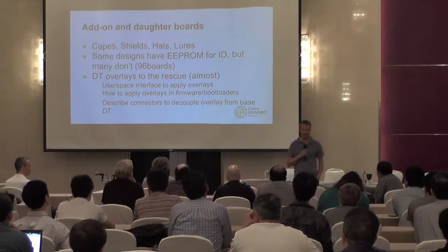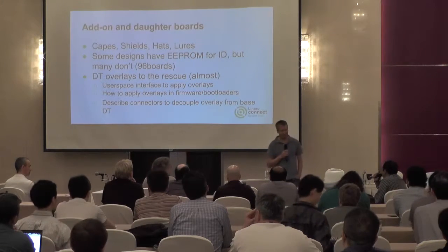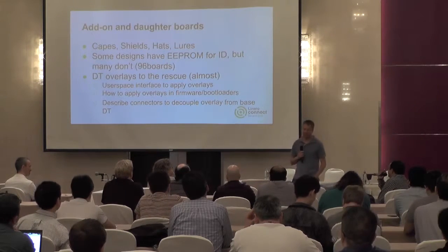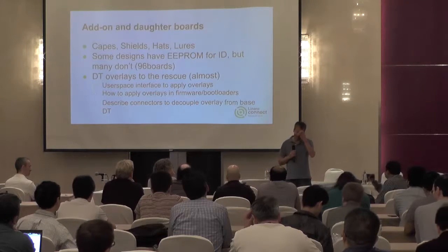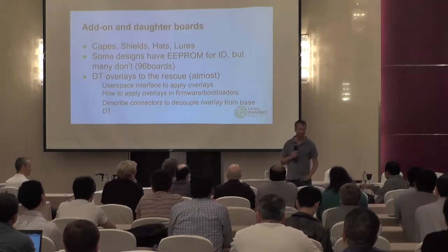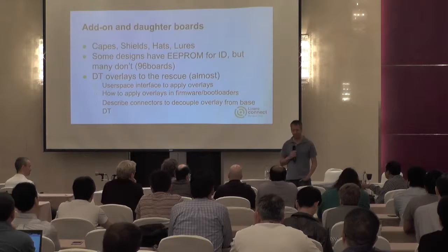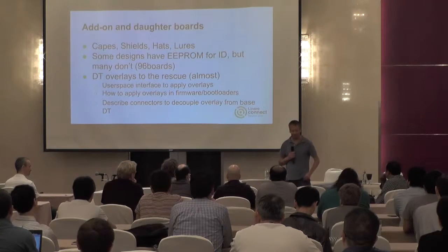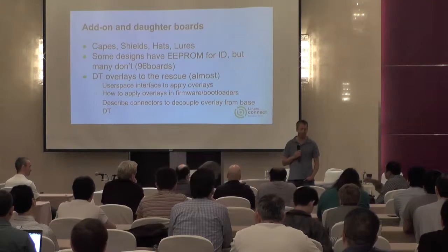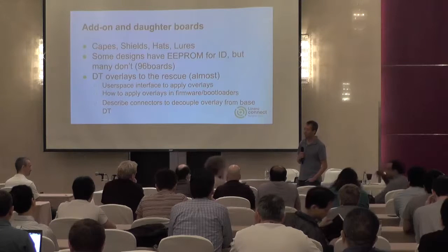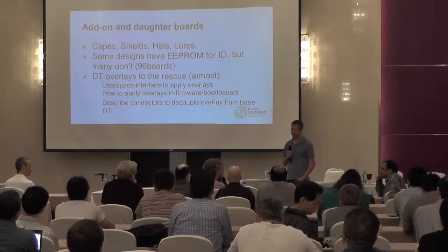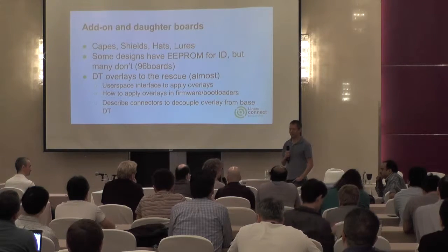Well, I would argue that libudev is standard for everything but Android. Yeah, but it is bulky. It's less needed if we're not talking about hot plug. So for the cases where it's static, trying to solve the udev problem is less important. And udev doesn't handle separate GPIO lines. It would handle the GPIO controller node at that level, I guess.